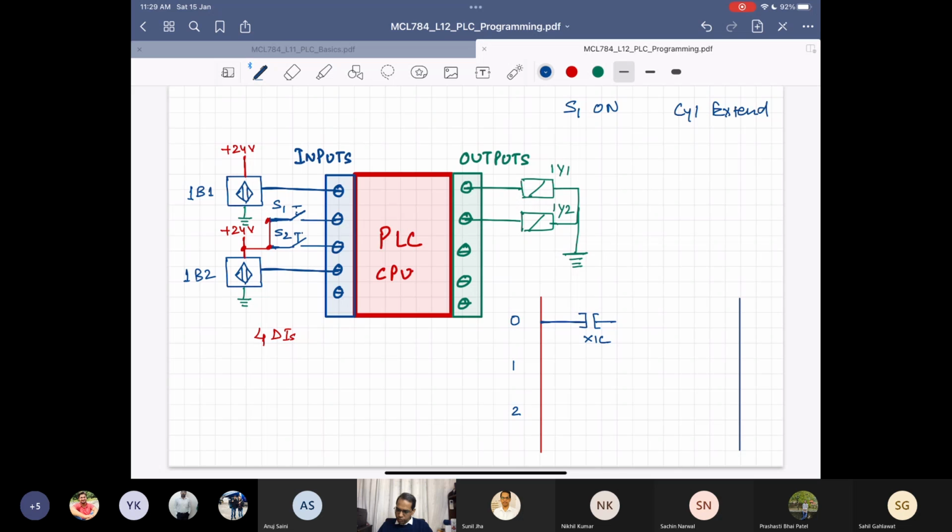So now I have to connect another instruction over here, and this instruction is your OTE instruction. Is this clear? Yes, sir. So we have used two instructions over here, one input instruction and one output instruction. When I use this XIC, it will be checking the state of the push button. XIC will read whether it is closed, because by default this is open. So examine if closed: if it is closed, energize the solenoid. We'll use S1 and mark 1 by 1 here.